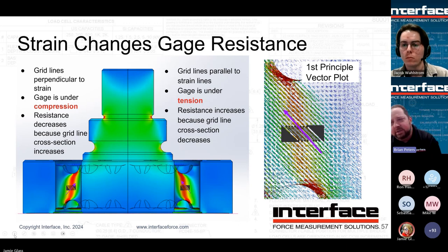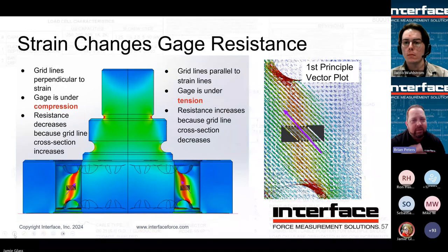Now our 1800 series takes it one step further and is what is depicted here, and it's a feature we call an integrated stud, where it's all part of the same machined element. We do this for some of our more demanding applications, for customers that really want the best performance. It's all one machined element, and it completely eliminates the chance of any variability in how that force is introduced much further away from the gauges and then propagates down consistently every time to where the bridge is.